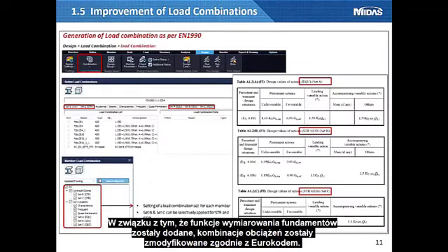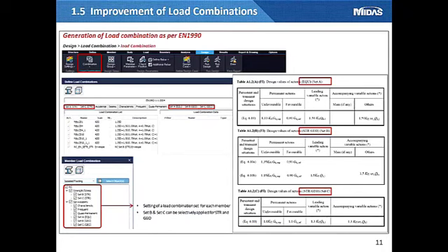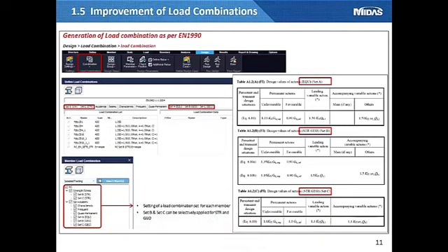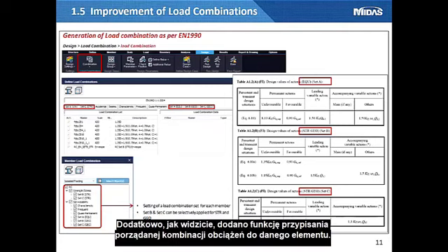Since the design functions of foundation members have been added, load combinations have been modified regarding Eurocode. Load combinations were added to review the serviceability of foundation, and the existing fundamental tab was further divided into sets. In addition, as you can see in this figure, there is a function that can be applied by assigning the desired load combination for each member.